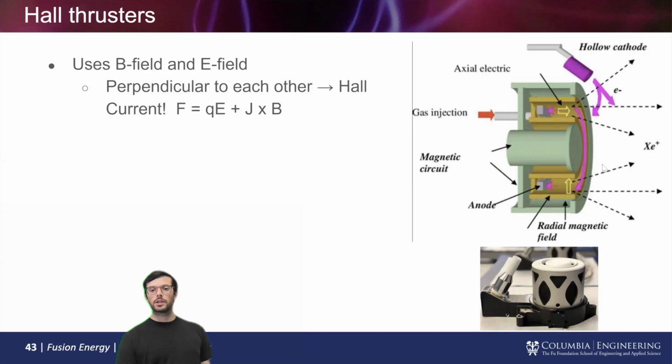So just to kind of ground you, this little Hall thruster is, you can see my hands, it's about that big. So it's maybe twice the diameter of a can of soda, about as tall. So it's quite small. This is a 300-watt Hall thruster. They go from 100 watts to maybe a few kilowatts. And this little channel you see, this one is pointing up, this one is pointing to the right, but that's this yellow thing you're seeing on your right. And you see this little cathode off to the side, that's the cathode hanging off the top. So that's what we're talking about.